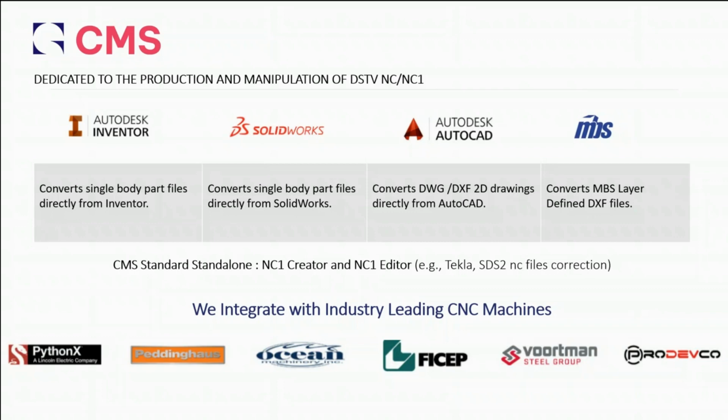So if you have any corrupted files, let's say for example from Tekla or SDS2, and your bevel descriptions are wrong in most cases, and you want to clean that up, you can delete the existing ones and apply the new ones. It's very straightforward. And I plan to show you an example at the end of our session.